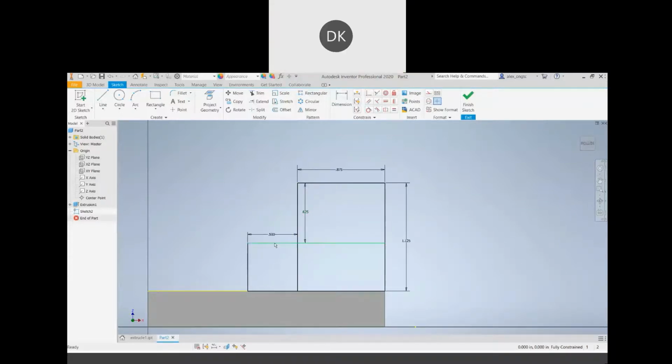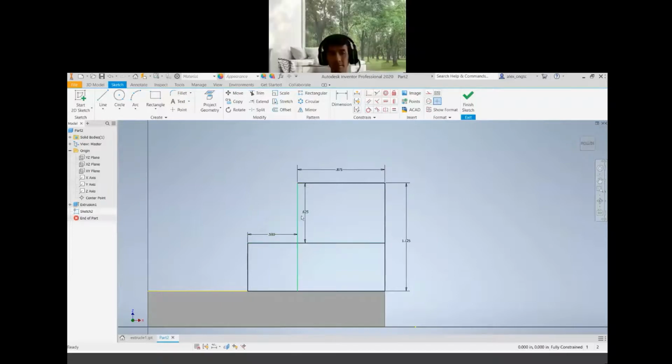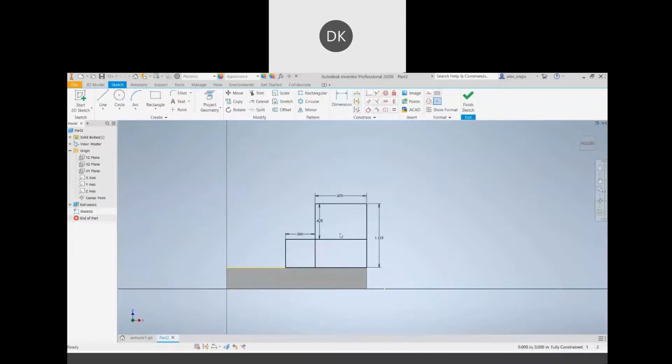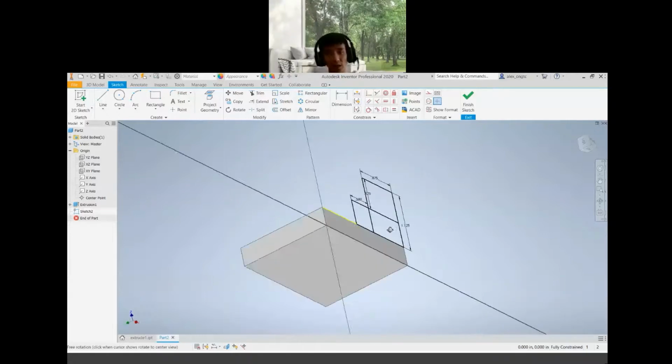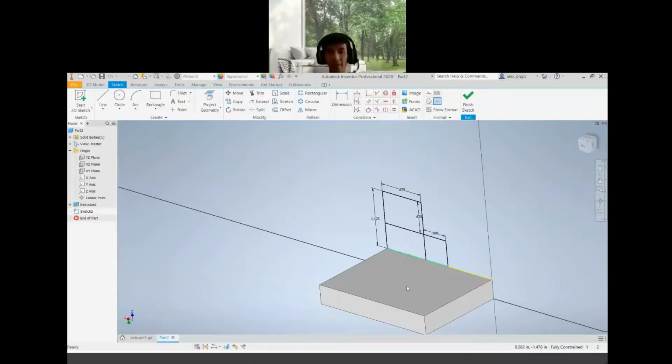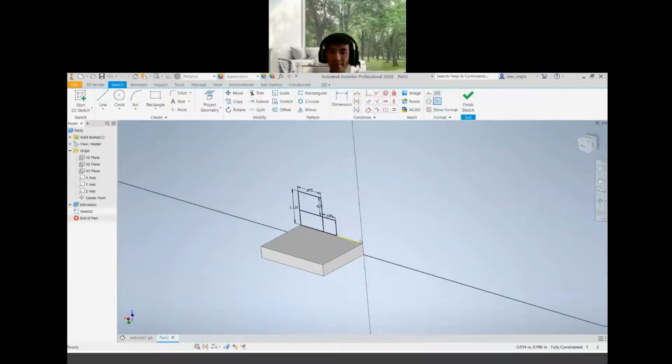So I have a question. Sure. Let's say if I want to start the sketch with XY plane, that means after that I don't have to use the view cube to change the angle view. Yeah, no problem on that. If you already select the default plane just now, then coincidentally you have that view already. So no need for you to do any navigation of the view.